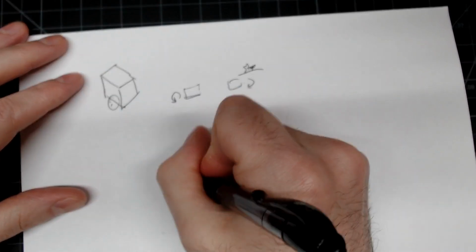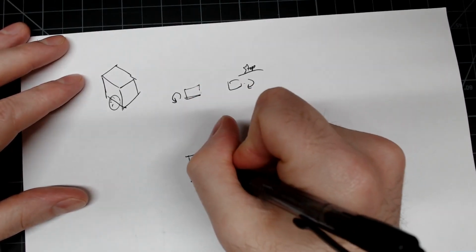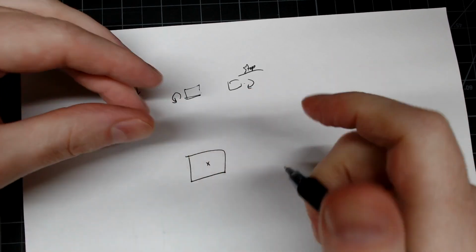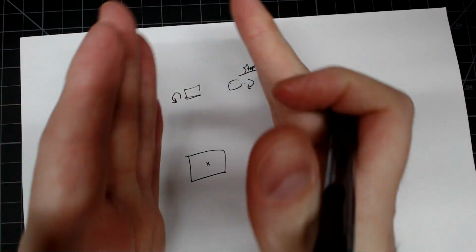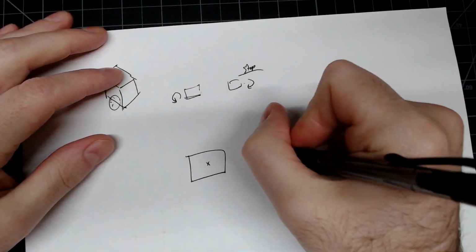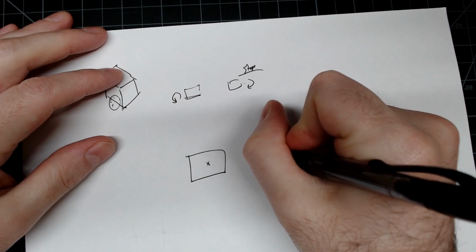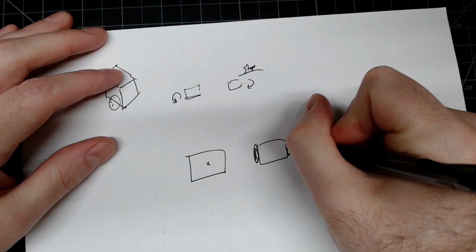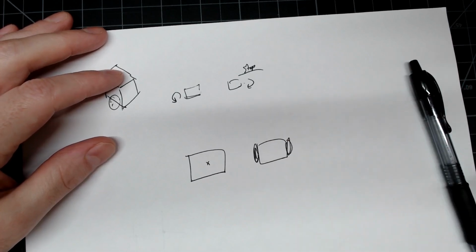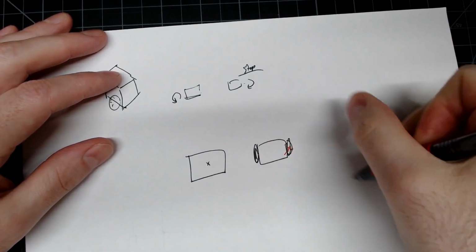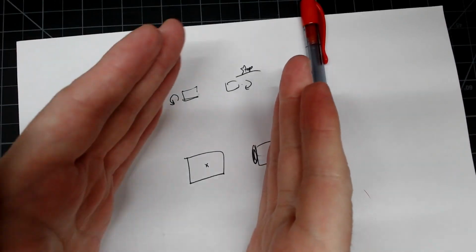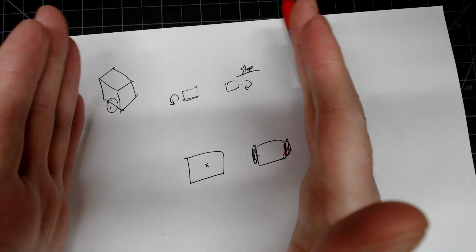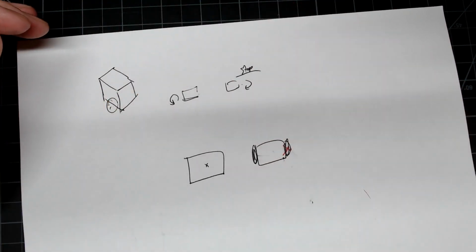So the nice thing, if I have a robot that's like this, just top down, is that my pivot point is here. If they're counter rotating, it just rotates perfectly in place. If I don't do that, then my best case is that I've got my wheel sort of here, and I've got my wheel here. If I'm turning to the right, this actually becomes my pivot point, right? Because it has to rotate on that point, so it's going to rotate around like that, as opposed to rotating like that, if that makes sense.